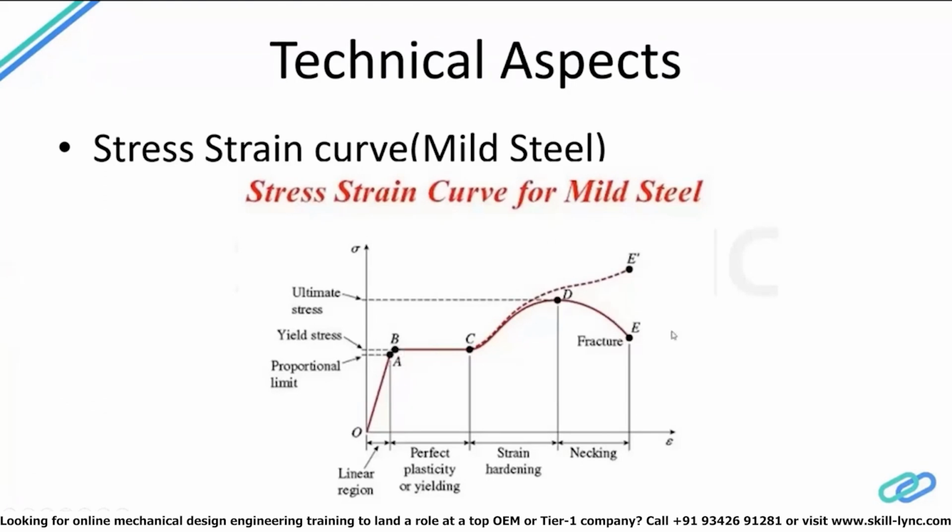So this is one important aspect of the material that we typically deal with in structural engineering. Unlike concrete, wherein you won't really see this long range of strain. Once the concrete has reached its compression capacity, it tends to crush, and that's a brittle failure, which we typically try to avoid, because that's going to be a sudden collapse of the structure, versus this kind of behavior, right? So what I'm trying to get at here is that we need to understand the material behavior properly. All of these are tested in laboratories, and therefore we come up with how the structures or members are actually going to behave because of these kinds of materials.